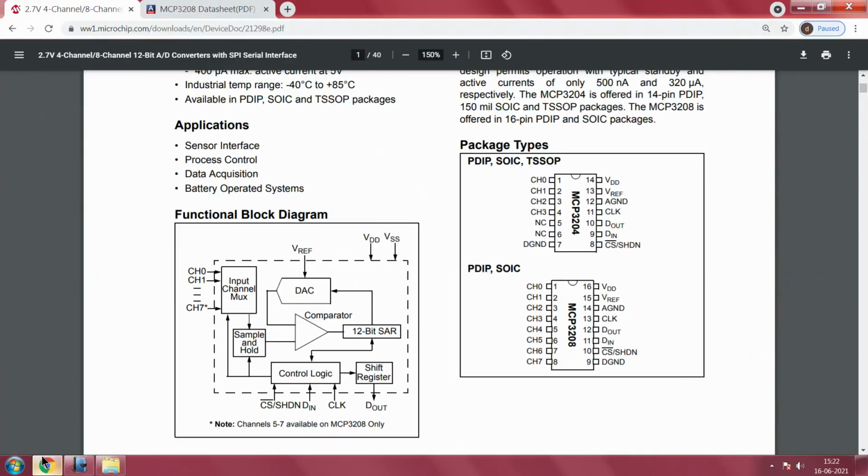Okay. So this is your comparator, and this 12 bit SAR is giving you the digital value, the code word that is held, for which the comparator passes based on the MSB and the other corresponding bit positions. So what will the DAC give you as an output? It will give you an output based on the reference to which it is fed.